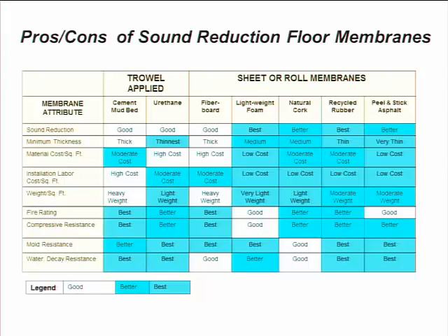Mold resistance varies depending upon the type of membrane as well. As we mentioned, exposure to water, if you're looking at running your soundproofing through the entire areas, which is a trend in most areas, in the kitchens and the bathrooms, you're going to want to take into consideration: is the membrane good when it's exposed to moisture? Does it cause problems with mold or mildew? Does it cause problems with bonding?